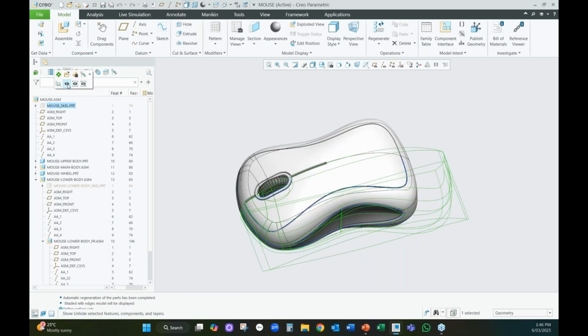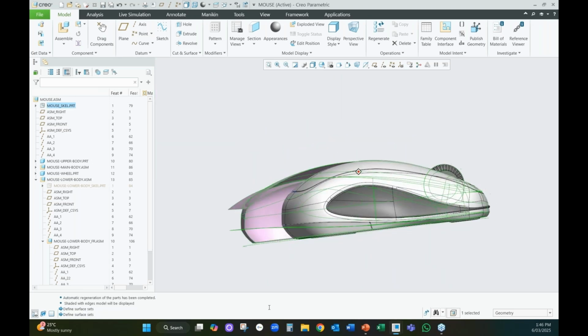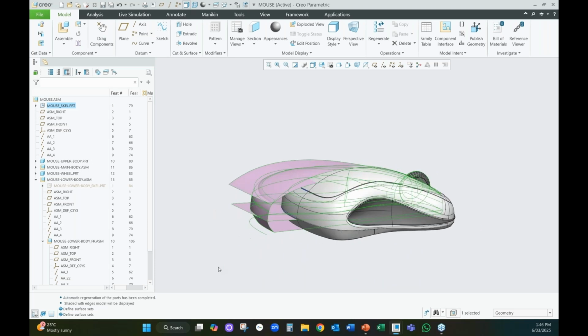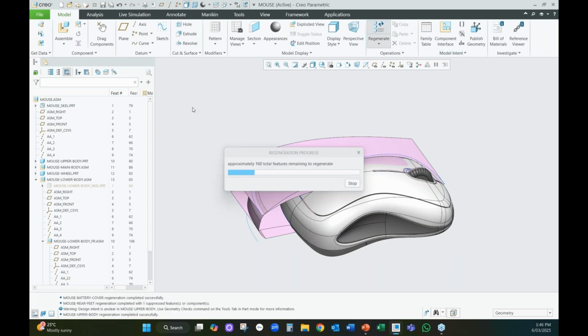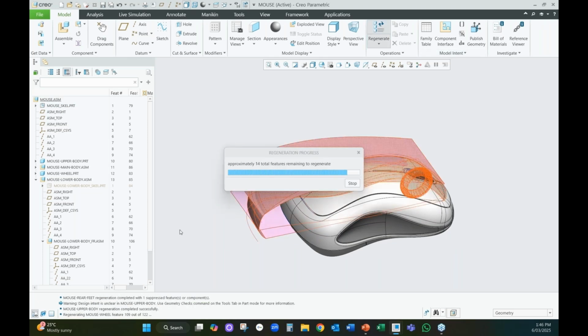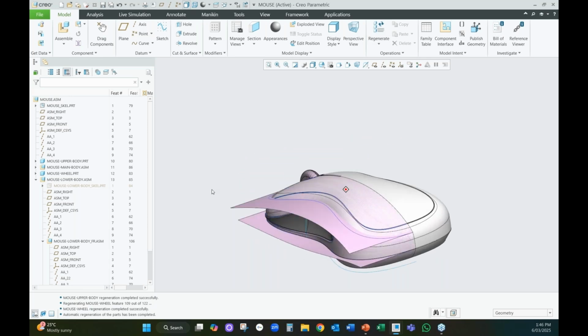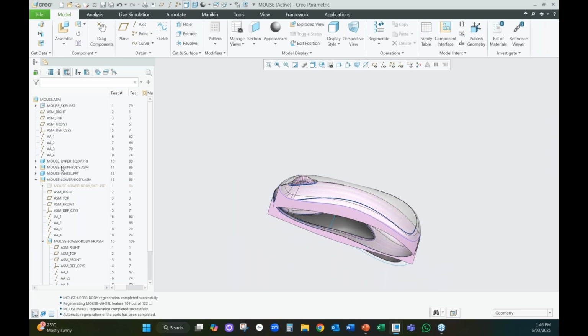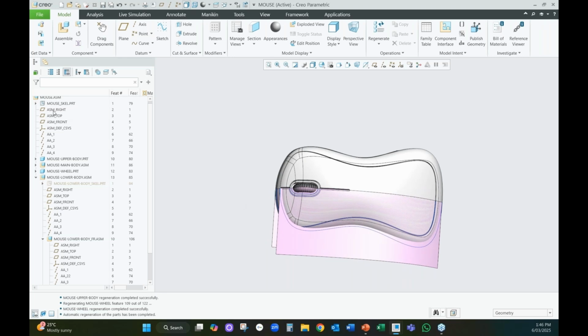If we go back to the assembly and show the skeleton, we can see the top level skeleton has increased, but the parts haven't. We'll come down and nervously press the regenerate button up the top. And so it's now filtering down through the top, regenerating all those parts. Fingers crossed, no red cherry bombs. So with one regeneration, I haven't counted the parts, there's probably 20 parts there. We have now done a significant design change in a matter of less than a minute.